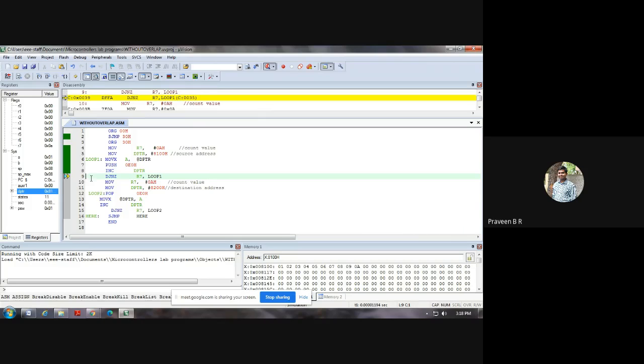Next, what is it going to happen? Next, it is going to check whether the register R7 is still having 0A or not. How does it check? It has completed one operation. What is that one operation that it has completed? The data 01 has moved to the stack. So it will decrement the data present in register R7. So R7 will become now A minus 1 is 9.